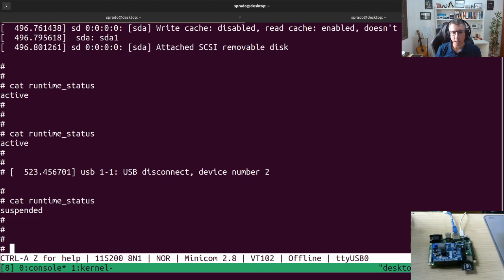So I'm going to show you here how that works at the CPU level, right? There is this framework in the Linux kernel called CPUFreq to manage this kind of feature. How does that work? Of course, you need some support in the hardware. The processor that I'm using is coming from NXP i.MX6. It has support for this, so I can scale down the CPU frequency if I want. And there is a driver in the kernel that provides this feature for me.